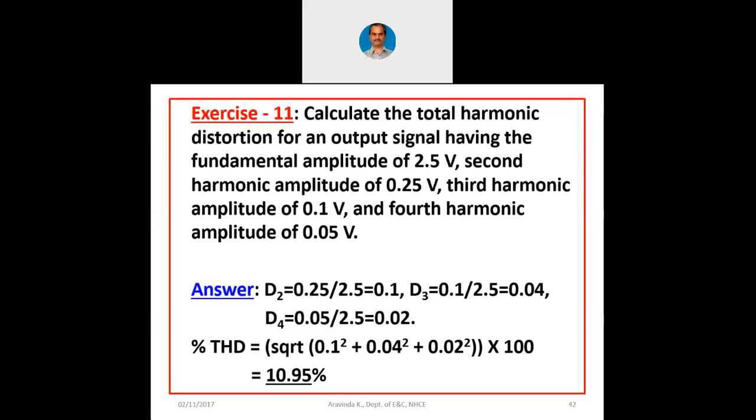In this example, this 11% distortion cannot be tolerated for a preamplifier as such, or even for a power amplifier also. If it is basically for music or for public addressing, now if there is 11% distortion, then the song which is sung by the singer, the voice will have a distortion when it comes out of the amplifier. The same music may not be enjoyed by the audience if there is 11% distortion. So definitely this particular example cannot be applicable to a regular audio power amplifier.